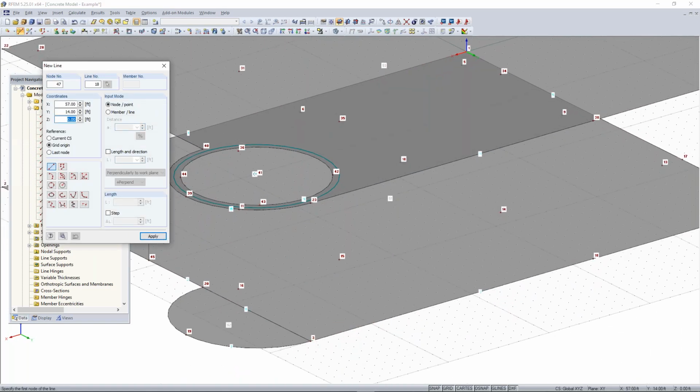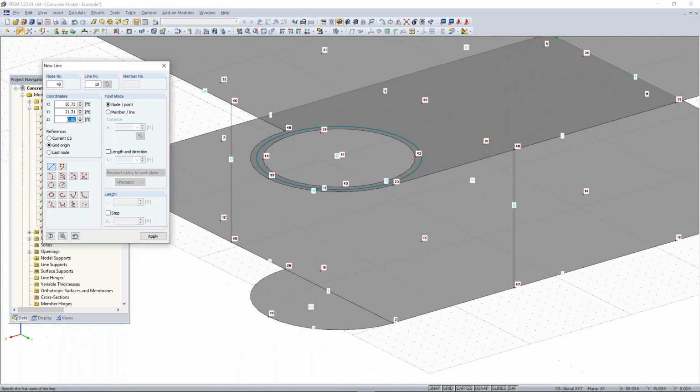And this one, I need to draw a line from 12 feet from node 3 here, so that's going to be at the coordinates 34, 40, 0. So let's go 34, 40, 0. And then I just want to draw this line all the way up to the ceiling slab. And you can see again, it snaps perpendicularly to the top there. Pretty easy. Then I can right click, and now all we need to do is connect nodes 20 here to